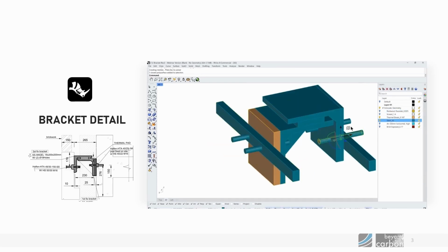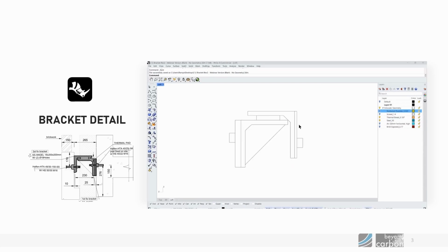And in places where they cut through the material, for example, the thermal break, we're going to use the Boolean difference command and delete the layers that are going to be overlapping. So we will continue doing this in the rest of the geometry, so it's ready for import into SimScale.